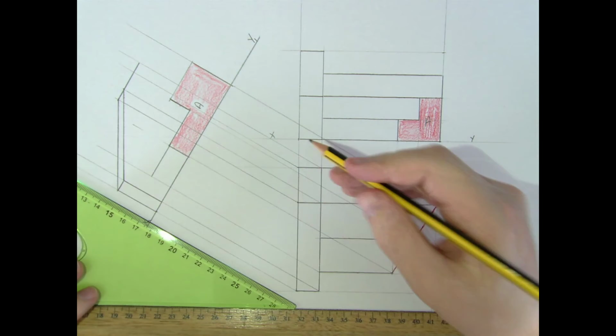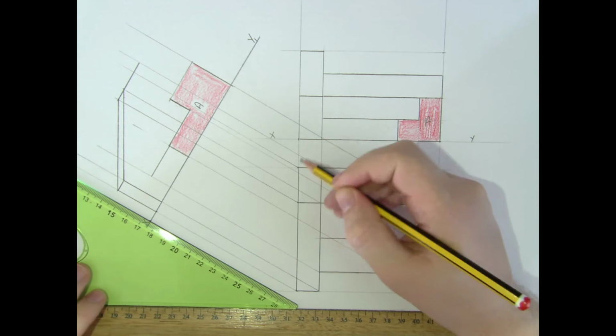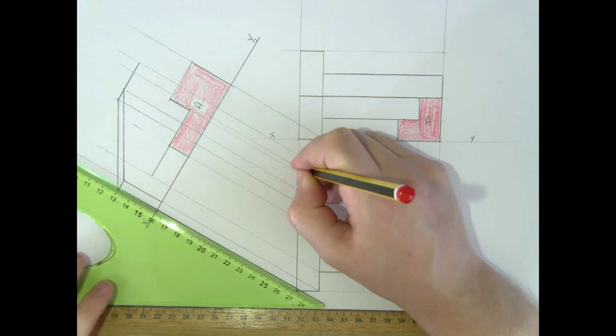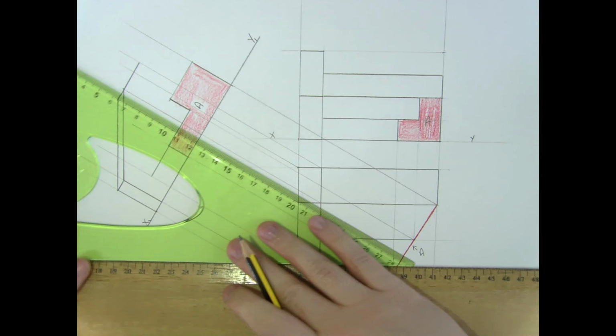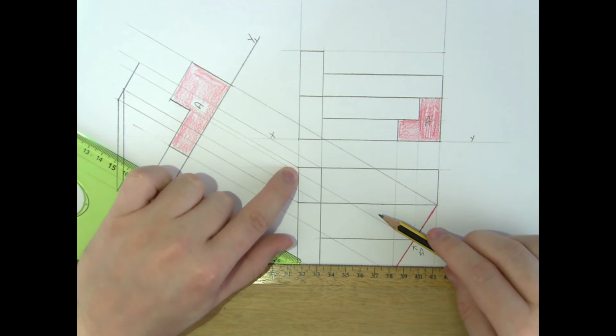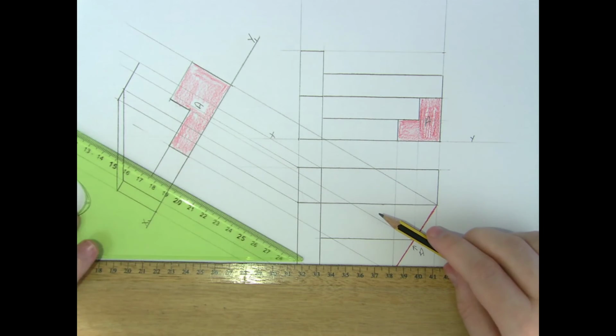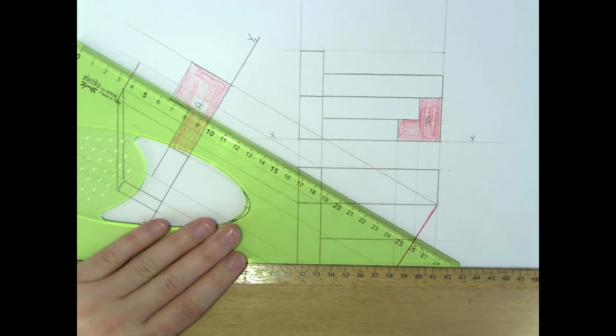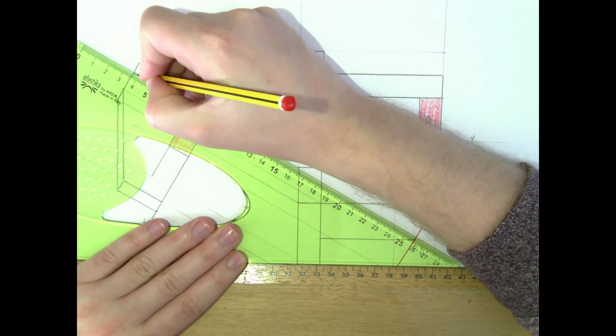One thing to note is this corner back here goes all the way down to the ground, which means there's going to be hidden detail representing that part of it. So when we're looking in here, this corner exists, but I can't see it, so I need to take that into account. It's a hidden detail line running the whole way down the back until it touches off the ground.